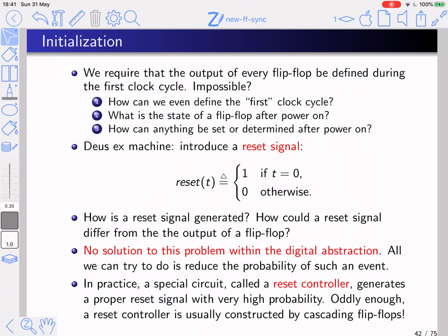And from that point, I restart the whole induction of the simulation. Okay? Good. So I have a signal that marks the first clock cycle, and I can, in fact, restart this marking by setting the reset to 1. And then I'm counting again from clock cycle 0.